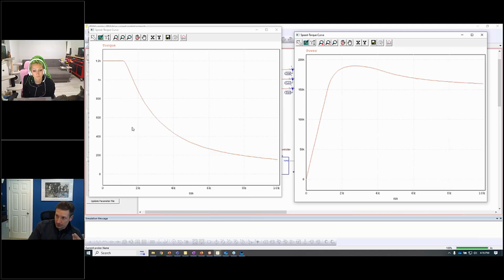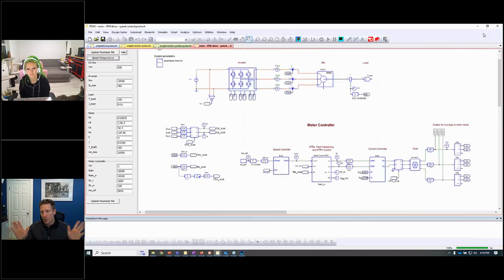One concept that's pretty apparent is you don't always get the same amount of torque. There's a torque rating at stall at 0 RPM, and then there's a power limit that runs here, and you get decreasingly less amounts of torque at higher speeds. And this is just a function of the power limit. There's a bunch of limitations that go into electric motors and their systems, you know, current, thermal, mechanical stresses, all that kind of stuff. So this information can pop out for you there. Now, thankfully for the FIRST kids, you don't got to worry about that.